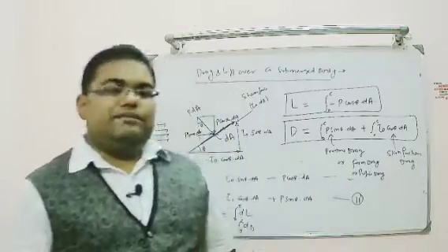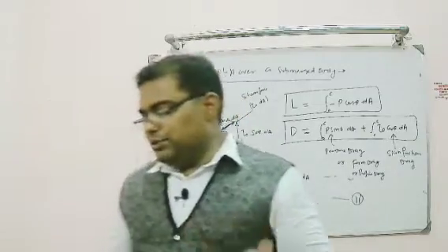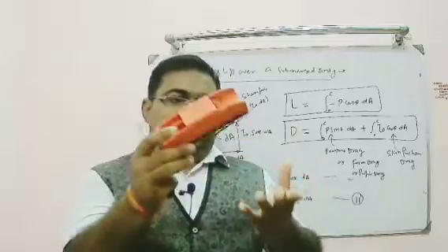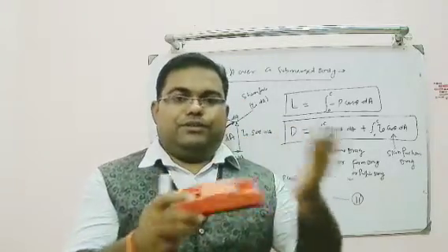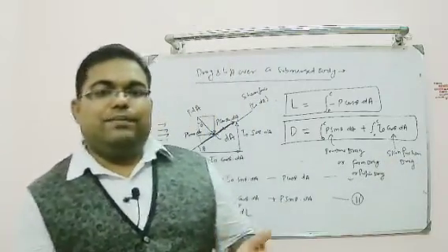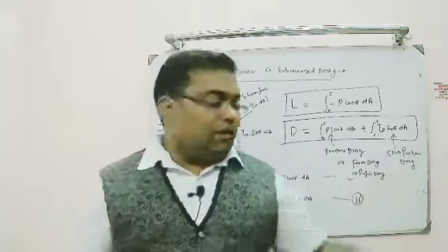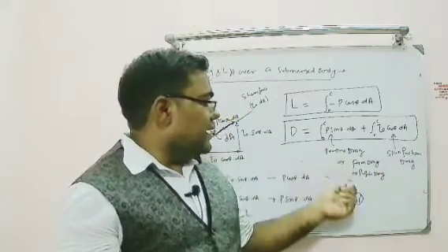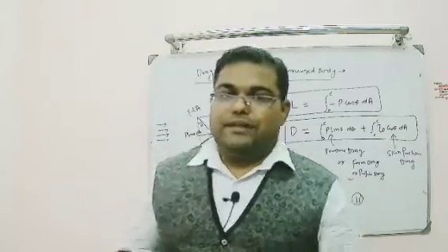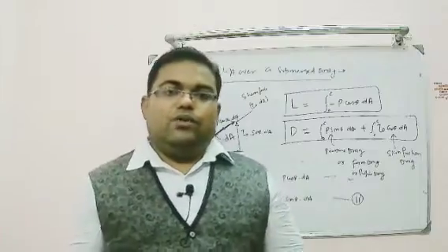Pressure drag further has two or three different kinds of things. Sometimes we say pressure drag is due entirely to the shape of the object, and flow separation happens because of that. And skin friction drag basically deals with the boundary layer properties and frictional effects. All these things come in skin friction drag. So total drag is a combination of these two, pressure drag and skin friction drag. Like that we can calculate lift and drag over any kind of object.